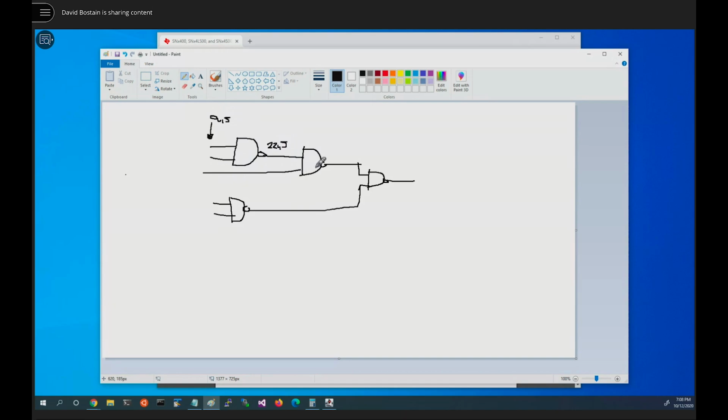So this guy is going to take 22 nanoseconds to get through. The signal here will change, but this guy relative to 0 is at 44 nanoseconds. This guy, of course, changes signals at 22 nanoseconds. He's going to go into this guy at 22 nano. He's going into him at 44 nano. And the result is going to come out at 66 nanoseconds.